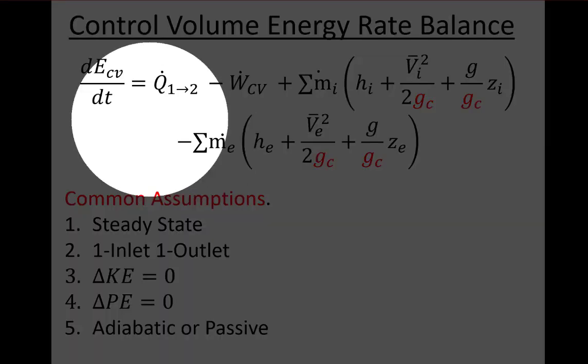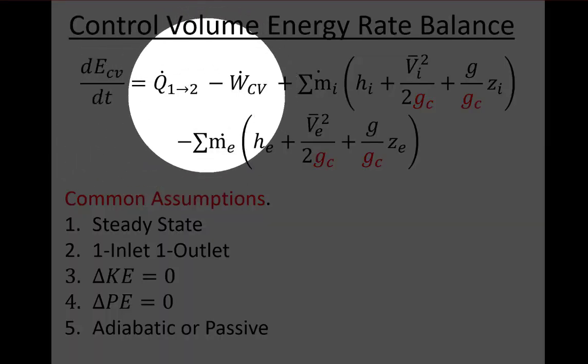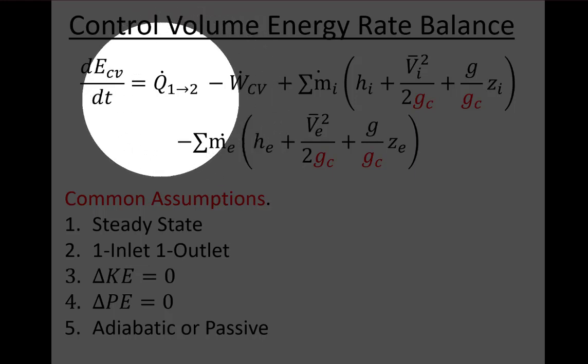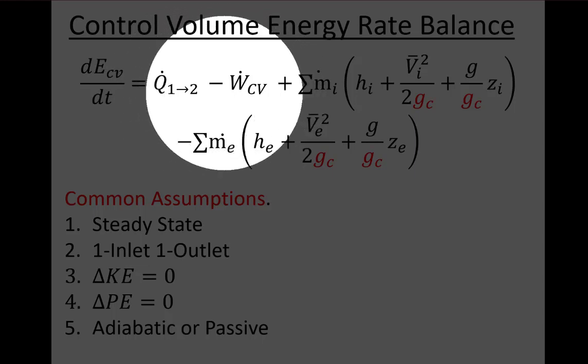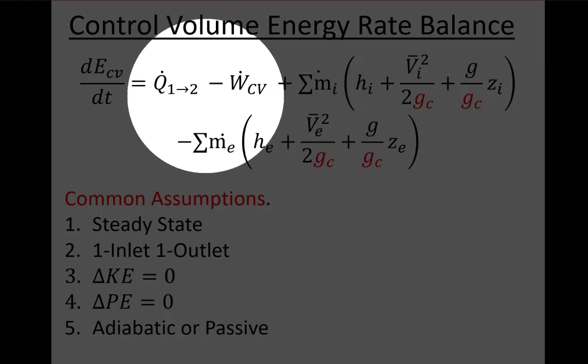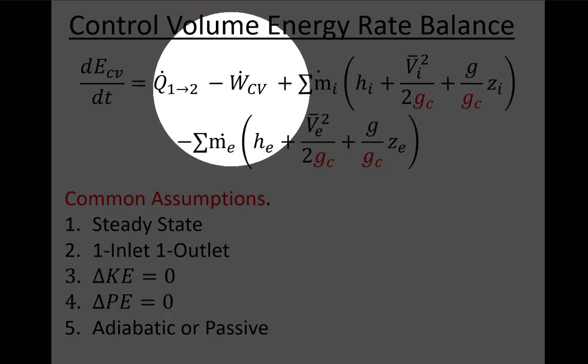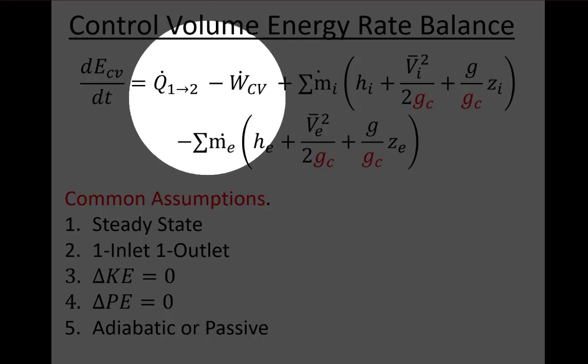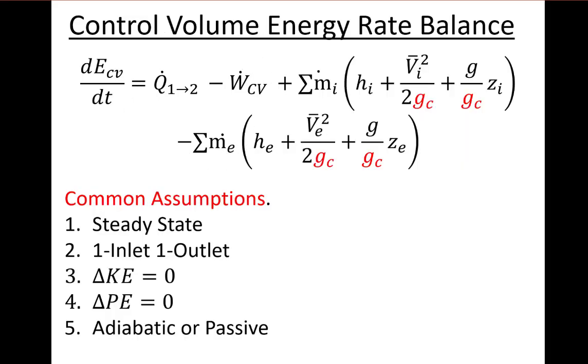Then typically with open systems, we'll assume that they're simple systems unless we're told otherwise. So a simple system means either heat transfer rate or power sticks around, but not both. Again, I can sort of disrupt you from this particular assumption by giving you something like a turbine that has some kind of heat loss with it. And then your equation won't just be W dot equals m dot times h in minus h out.